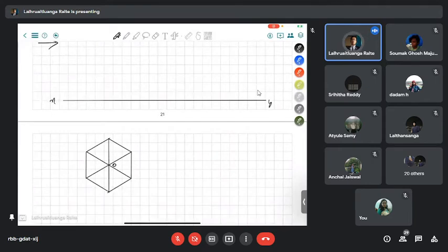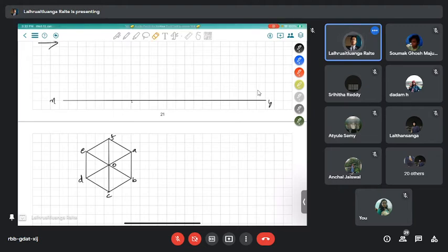Let's say it's the line AB, which is going to be the one that's anchored to the ground. All right, so we are aligning this perpendicular to the XY line, so that when we tilt it, that will be the anchorage, and the axis will still be parallel to the vertical plane.